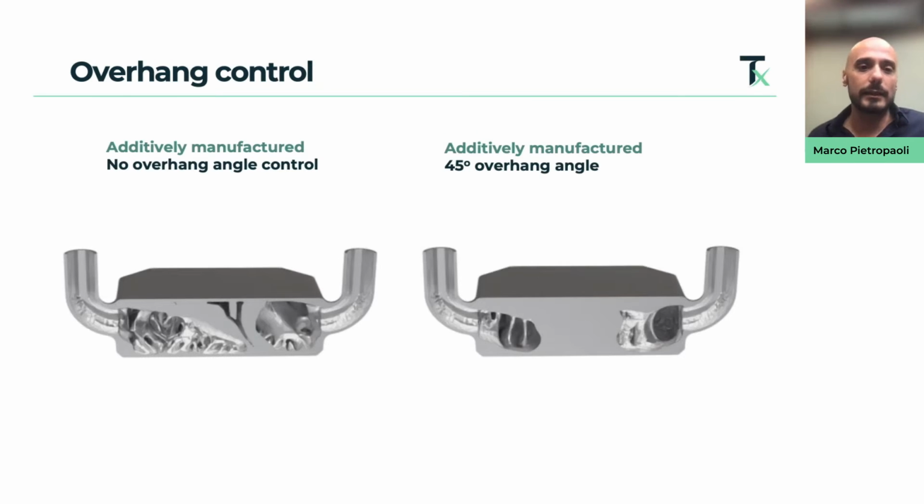I'm going to start by showing the capabilities of our platform. I'm generating an optimized design in 3D, suitable for additive manufacturing. I want to emphasize how, within the space of additive manufacturing, we can control the manufacturing constraints, for example, the overhang angle. If I want to minimize or reduce to zero the region that needs support during printing, I can input the overhang constraints literally in my software.